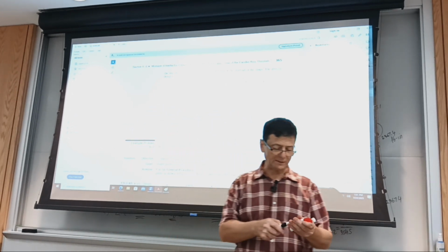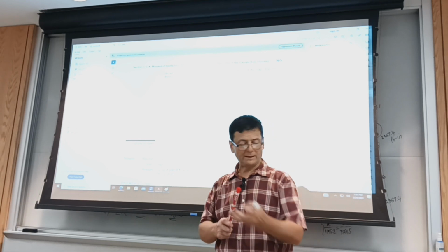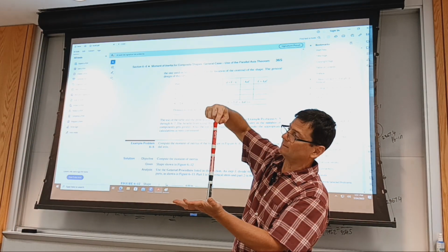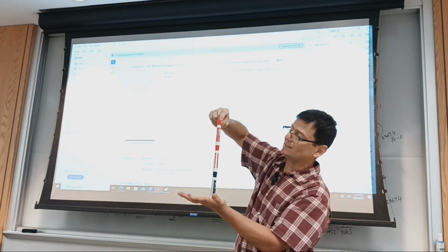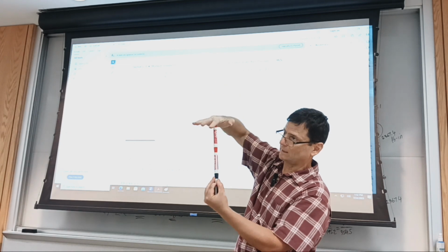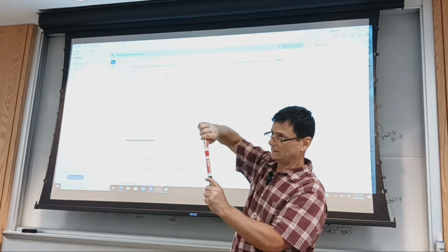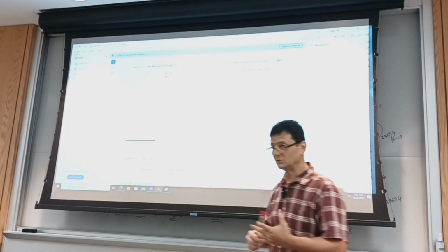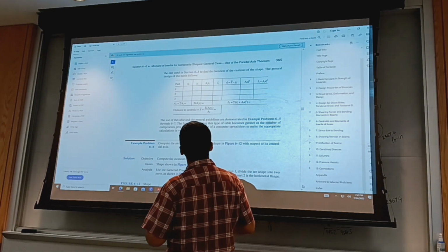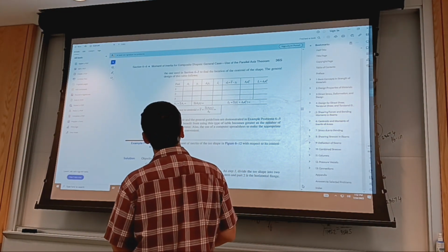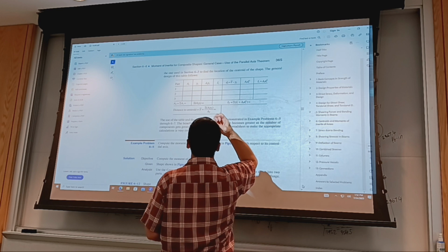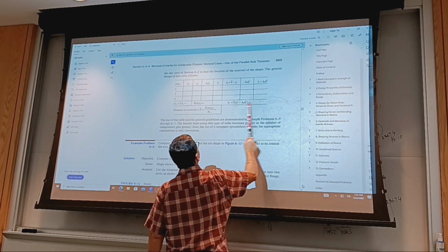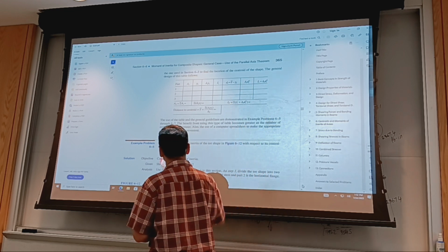Okay, it's like having a column, if you can watch. So I have a column, and instead of loading it axially, I load it on the side. And loading it on the side adds bending to the column instead of just compressive load, and that can cause failure earlier. It does not hold the same amount of axial load when you add bending by not having centroidal loading.